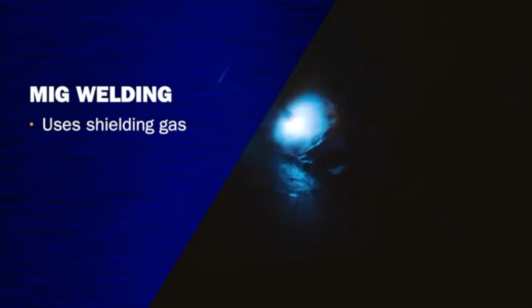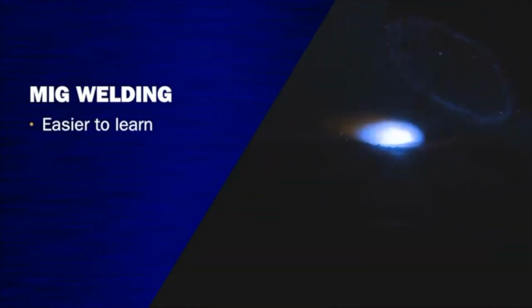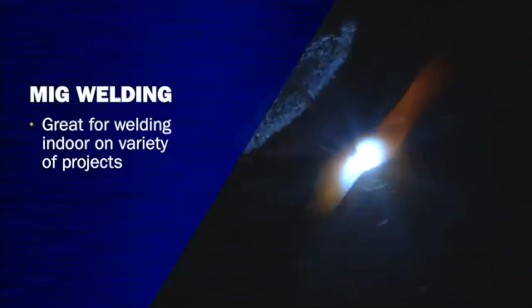So let's talk about MIG welding. In MIG welding, the filler metal is your electrode, and it's on a spool of wire. It is also a shielding gas process. The advantages are that it's much easier to learn because you preset all of your parameters, it's much cleaner because you don't have any kind of slag, and you can hit a wide variety of metal thicknesses. So if you're in a garage or your shop, that is a great process to use.